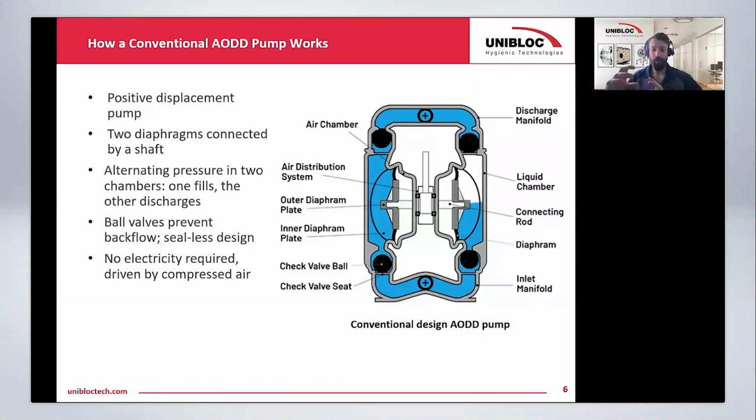I even had a customer who wanted to mount his pump sideways above a 55-gallon drum so he could keep it as close to the drum as possible. And then he called me upset because it was just spraying water everywhere and not working like it should. And so I had to tell him, no, you have to make sure your pump is oriented in the right direction. You can't mount them whatever way you want.